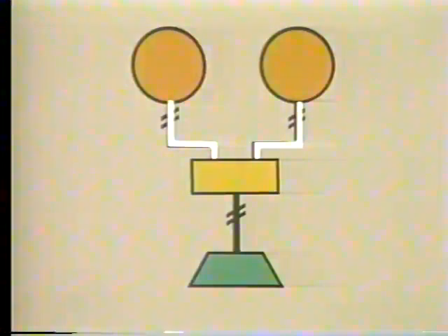In a ratio control system, the controller uses one of the input signals to establish set point. The ratio controller compares the other input signal against set point. If there's a difference between this input signal and set point, the controller produces a corrective output signal that represents this difference. The corrective output from the controller is sent to the final control element.